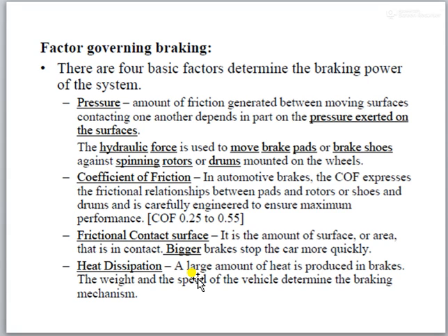So our duty is to dissipate the heat produced during the braking action as early as possible. If we employ such a mechanism to remove that heat as early as possible, then braking efficiency is increased. For that purpose, we can make a proper ventilation in our disc brake assembly, or we can make a proper air circulation around the drum. Okay, we can add fins.